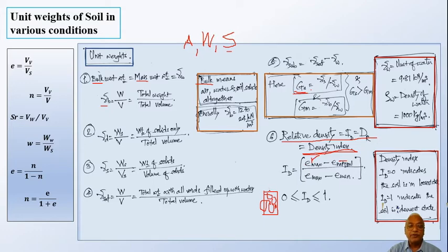Now try to put some effort, that is you use the rammer, compact it as tightly as possible, and then you try to find out voids ratio. In such case, obviously all the voids are completely filled up with very tightly filled soil particles. Voids will be less. So in such case also you try to calculate voids and voids ratio, then it will be E minimum.